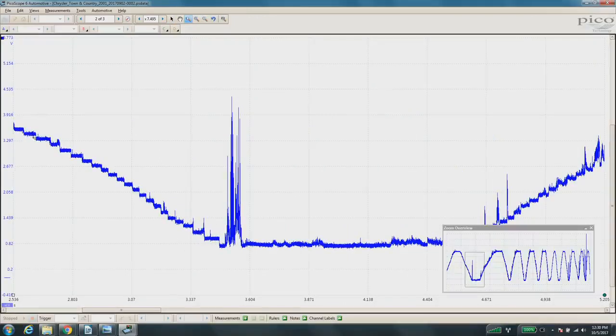So as our signal is ramping down by whatever, a tenth of a volt or whatever it might be, maybe it's 1%, as we get down to here, all of a sudden we have a voltage spike here. The computer sees this spike as the same as whatever voltage is over here. Or let's go to this one here. So this spike right here is being seen as the same level of this. If it were to last long enough, this could change our fuel gauge from, if it's actually empty or full, it could read half or vice versa. We're picking out these intermittent problems here.